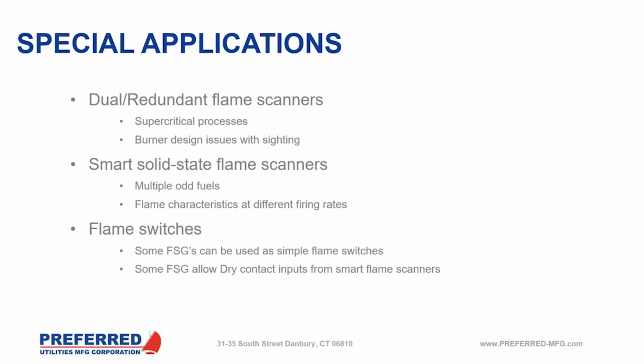And that's good. If you have one fail, then the other may hold you up. Another reason, though, to record flame signal strengths: usually you're going to have a stronger signal with two in parallel than you will with just one. So that can kind of tell you what's going on there. But obviously in checking out a system, that's where you would want to blind one and make sure that the signal changes. But you need to know that you can actually have redundant flame scanners.